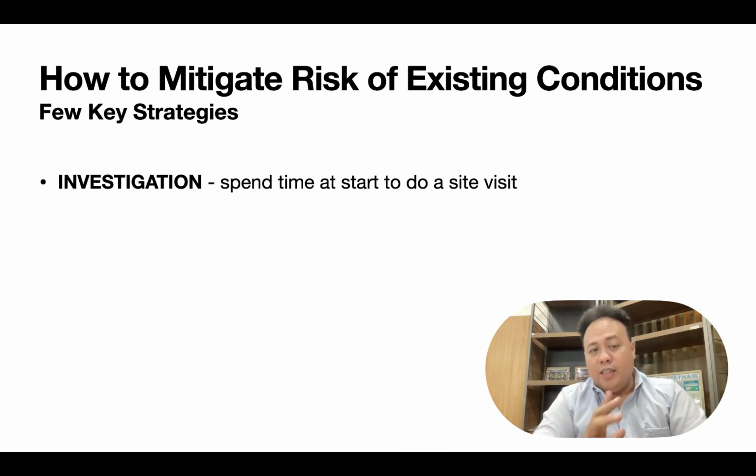First, investigate. Spend time to do a site visit before you cost anything. Go to the site, do a site visit, then at least you can see and lessen some of the risks, the unforeseen items that you may add on to the works later on.